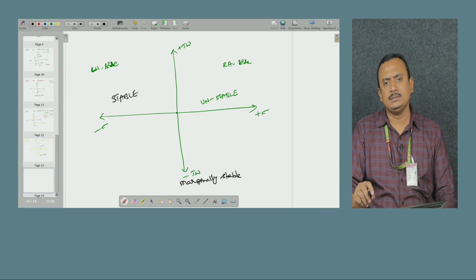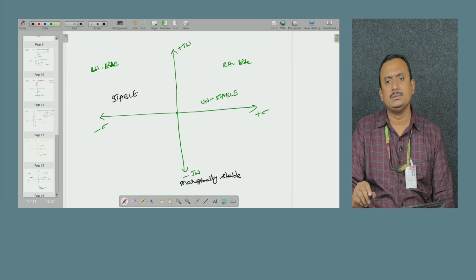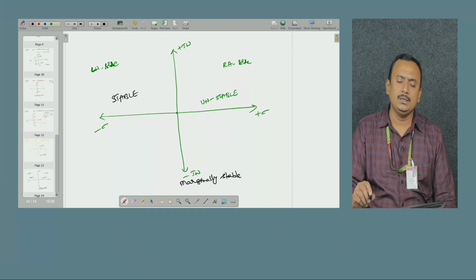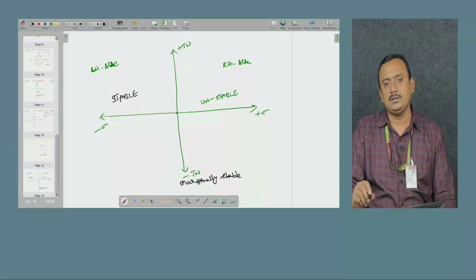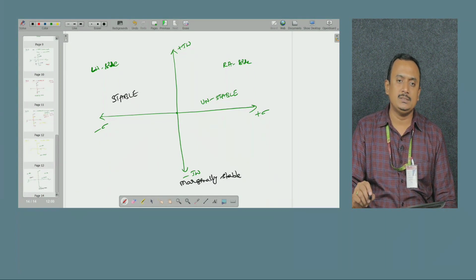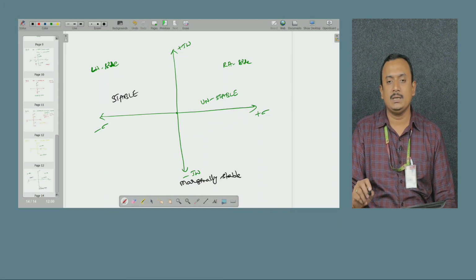The conclusion is, for the given transfer function, after finding the zeros and poles, you place those poles and zeros on the S plane. Anyhow, zeros will never affect the system stability. We are concentrating only on the placement of poles. If at least one pole is on the right hand side of the S plane, then we can say the system is unstable without looking at the remaining poles.